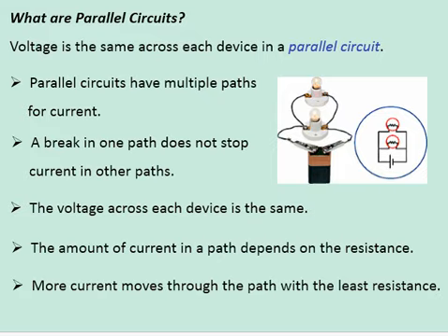Okay, so now let's look at parallel circuits. What are the rules for parallel circuits? Well, the idea with the parallel circuit is that the voltage drop across each of the devices in the circuit is the same. Unlike with the series circuit, where the current is the same through the entire circuit. Here, the voltage drop is the same across every device in the circuit.